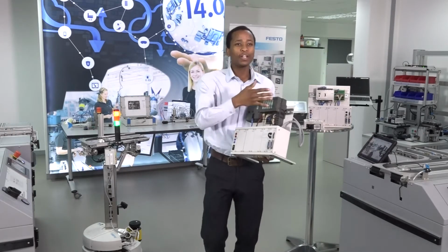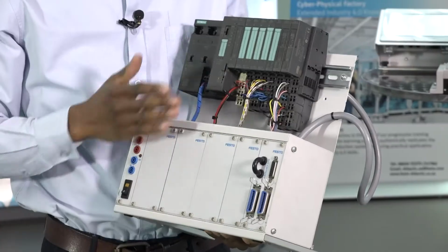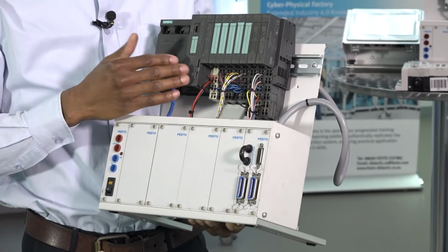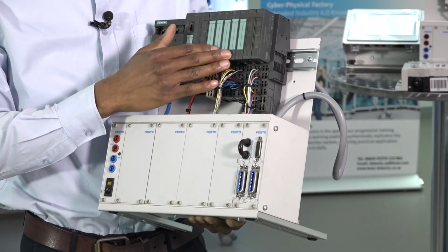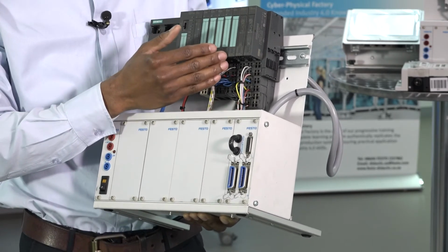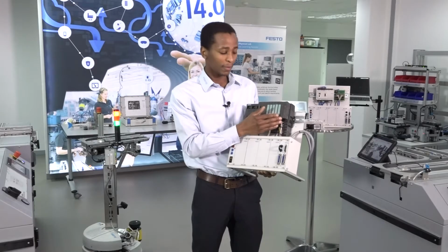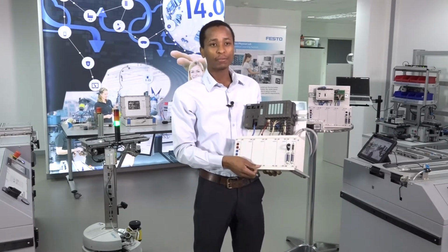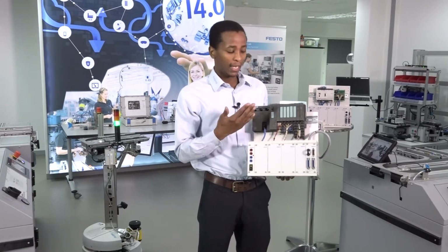Now, Festo isn't the only manufacturer of PLCs. Siemens is one of the very commonly known manufacturers of PLCs. This is ET200S. So much like the CPX, ET200S is flexible in that you can plug in different IO modules. In this case, I have about 4 digital inputs: one module has 2 digital inputs, so I have 4 of them. And then I have an 8 digital input module, and I also have an 8 digital output module, 2 of them. This way I can plug this into a machine such as the MecLab, if you're familiar, or the MPS, modular production system. Then I write the code to load it into this, and voila.